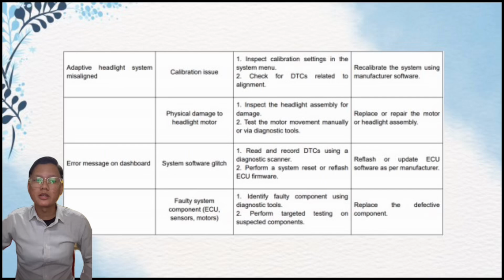Last but not least, error message on dashboard. Could be because of a system software glitch. So, first read and record the DTC using a diagnostic scanner, then perform a system reset or refresh the firmware. Refresh or update the software as per the manufacturer.